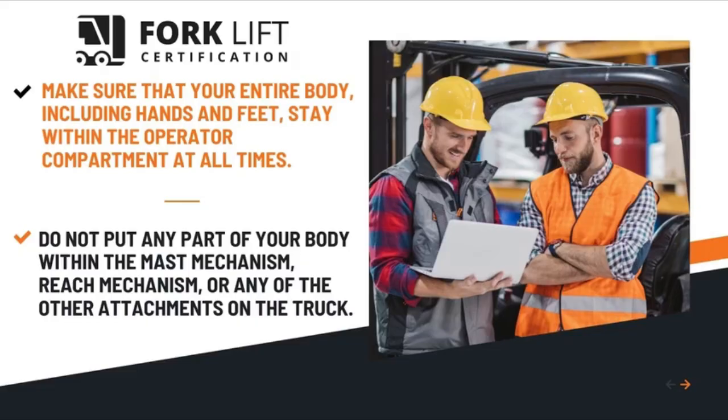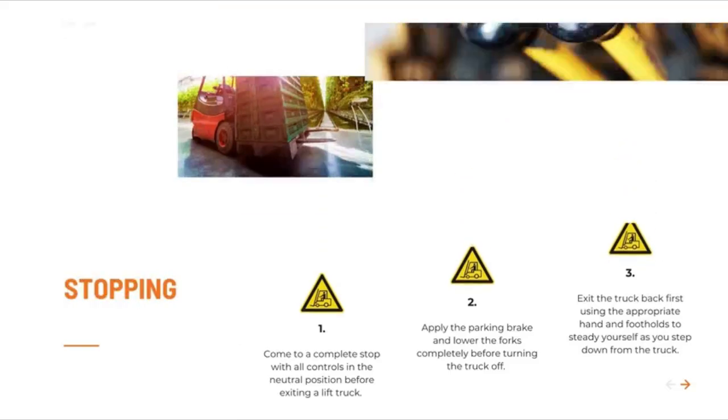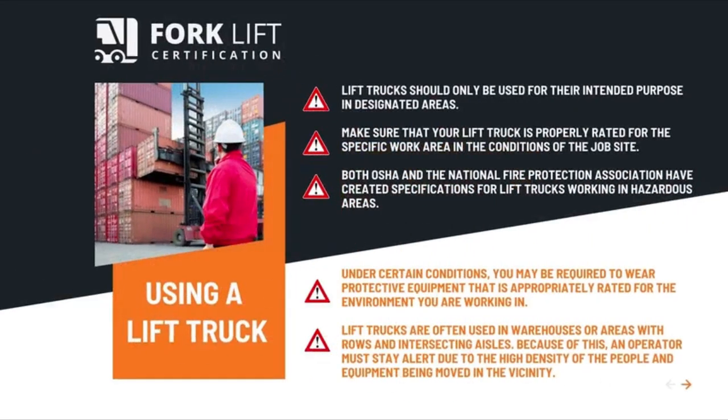Do not put any part of your body within the mast mechanism, reach mechanism, or any of the other attachments on the truck. Stopping a lift truck. Come to a complete stop with all controls in the neutral position before exiting a lift truck. Apply the parking brake and lower the forks completely before turning the truck off. Exit the truck back first using the appropriate hand and foot holds to steady yourself as you step down from the truck.